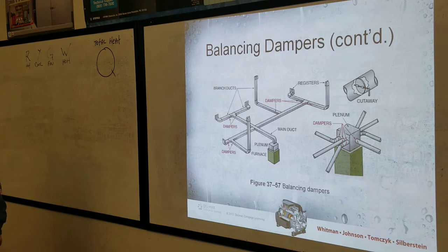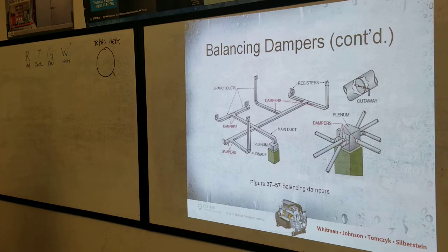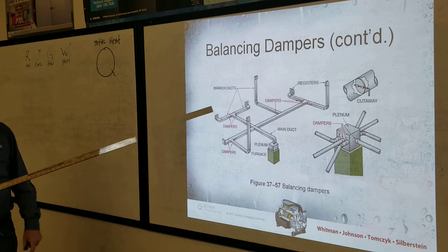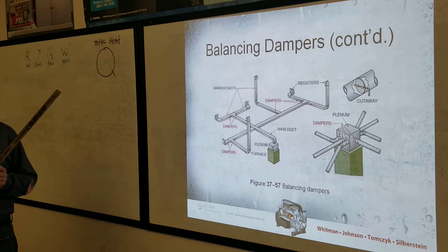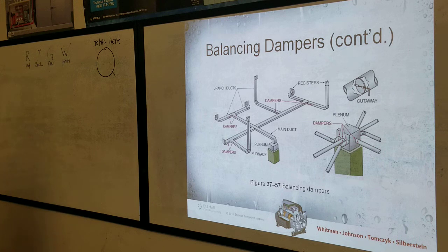I've done air balancing. We weren't certified, but we told the customer that. Actually, with Keller Motors in Hanford, he called up, he had airflow problems, and he said, can you come and do an air balance? And my boss says, yes, we can. We're not certified, but if you have the plans, we can do an air balance for you. So me and another guy went out there, and we looked at the plans, and then we opened and closed all the dampers and balanced each one with the flow hood. And we got it according to the plan. Nobody had done an air balance in that place.